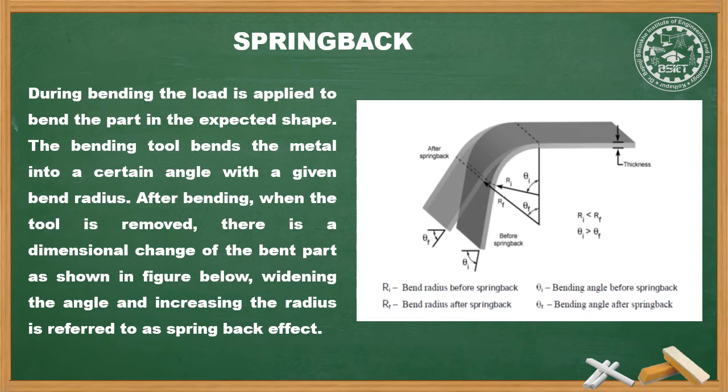According to the plastic deformation theory, the material is divided into two zones, the elastic zone and the plastic zone. The elastic property tries to maintain the material in the initial shape, whereas the plastic property tries to retain the material in deformed shape. In a sheet metal bending process, the bending load increases until the material exceeds its limit and enters the plastic deformation state.